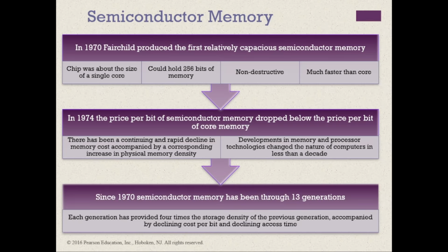In the 1950s and 1960s, most computer memory was constructed from tiny rings of ferromagnetic material, each about a 16th of an inch in diameter. These rings were strung up on grids of fine wire suspended on small screens inside the computer. Magnetized one way, a ring, which is also called a core, represented a 1; magnetized the other way, it stood for a 0. Magnetic core memory was rather fast. It took as little as a millionth of a second to read a bit stored in memory.